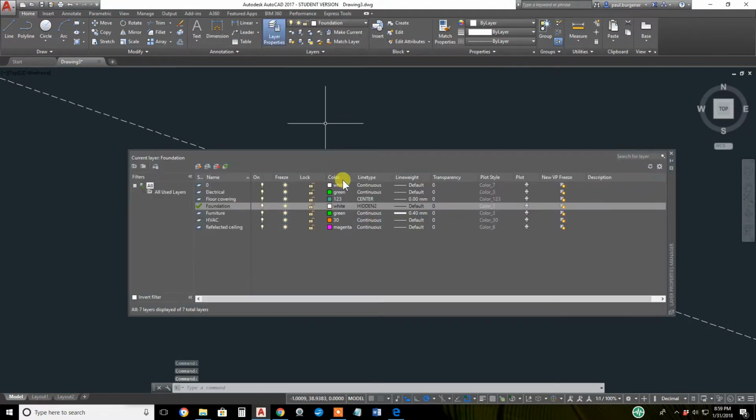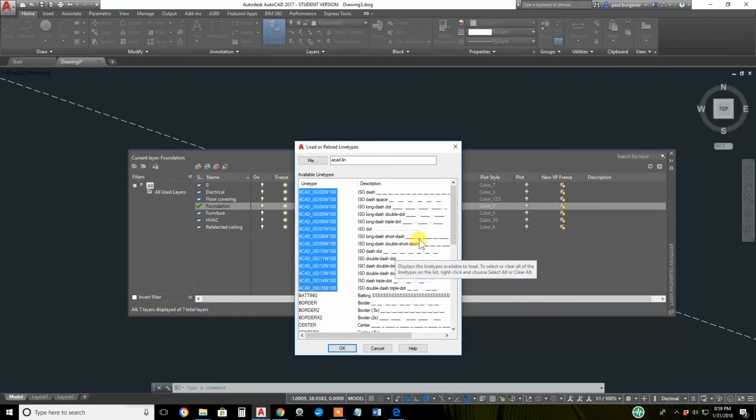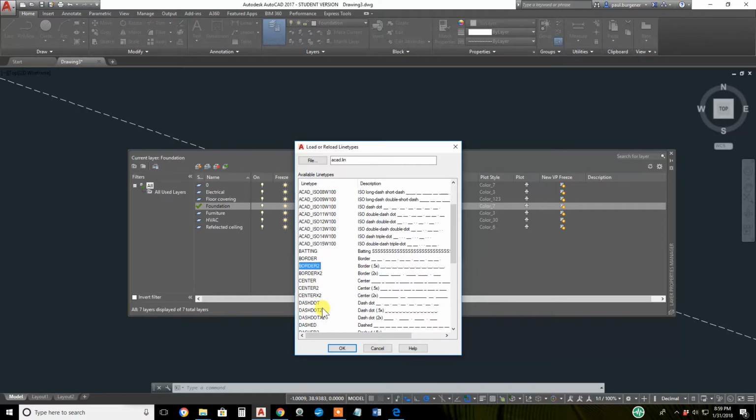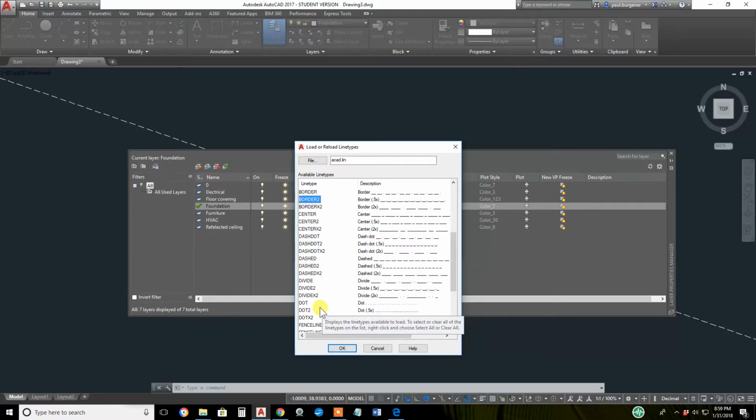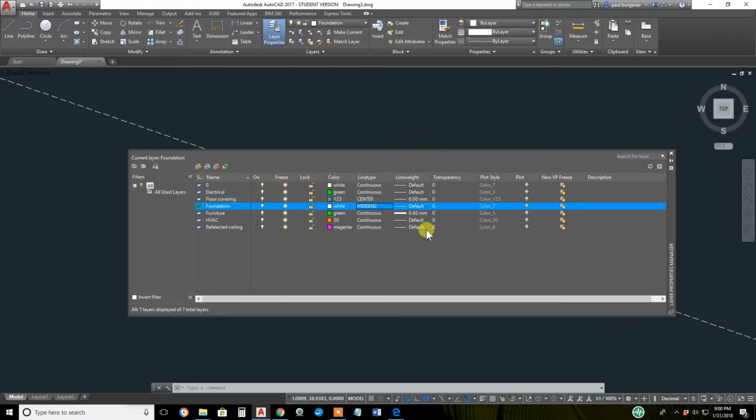Keep in mind the line types in the top of the list here, they need to be super long to show the dashes and the ink of them. They're made for much, much longer lines. The ones with the simple names, border, dash, dot, divide, those are for more handheld sized objects, assuming an AutoCAD unit represents an inch. What else? That's about it.